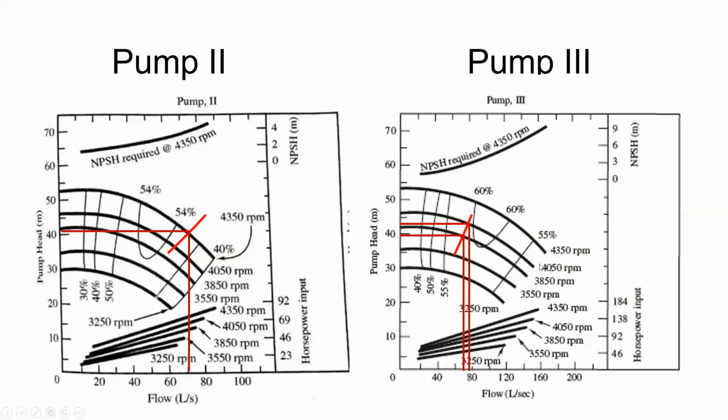And then at this higher RPM, so 40, 50 RPM, we're looking at maybe 75 liters per second, something like that, with these various pressure heads. We know that we have at least 20 meters that we have to overcome. And then I guess our system curve accounts for the pressure and the elevation difference. So here's some options. I think we basically have pump 2 operating at 40, 50 RPM, and then pump 3 operating at these 2 different RPMs would meet our flow rate requirements.